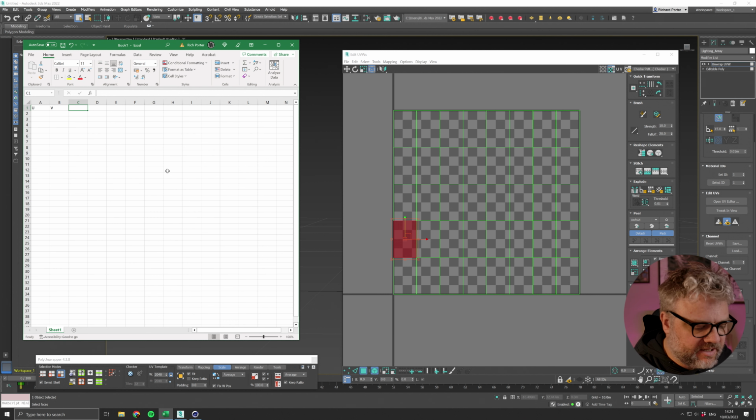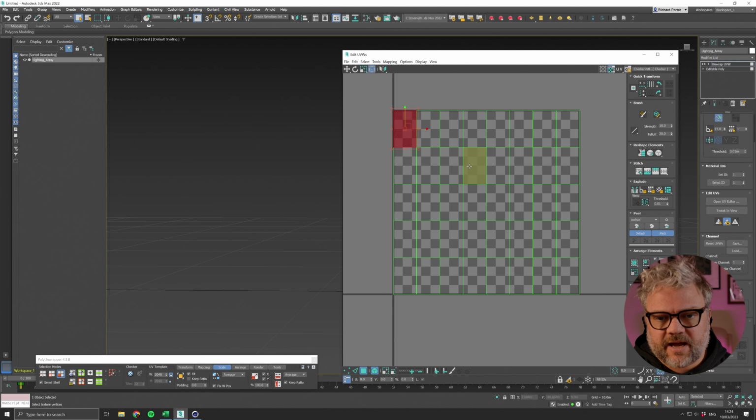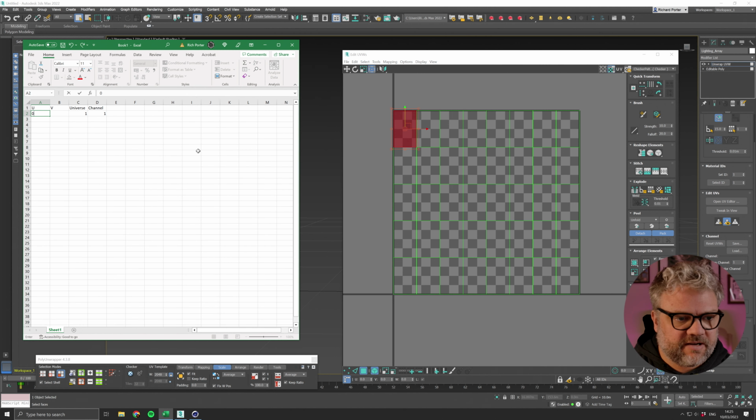The third bit of data we need is the DMX universe. So in order to not confuse our two U's, I'm going to give that its full name, universe. And then the final one is channel. You can get this information from your lighting team, or if you've rigged and set up your lights, you may know this information already. To make life easy for us today, I'm just going to start on universe 1, channel 1. So we're going to start with our first light, or first pixel in our array. So as mentioned, that's going to be 0, 0.